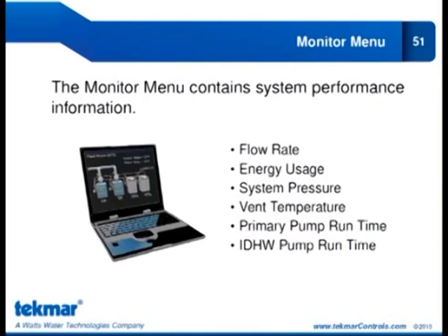Another thing you might want to be careful about is that if you begin to support energy, you're going to have to be a lot more confident of the accuracy and turndown of the meter. Absolutely. And I'm not familiar with Grundfos because we're kind of Bell & Gossett people. Honestly, it's a relatively new type of meter as well, so we have limited exposure with it. You're going to have to be careful when you recommend meters.